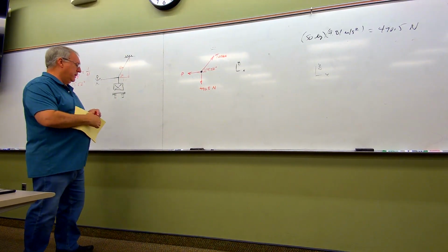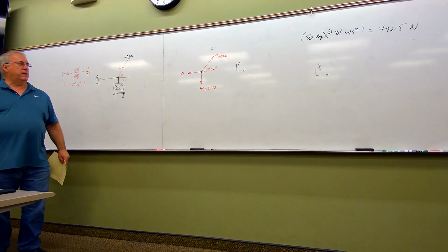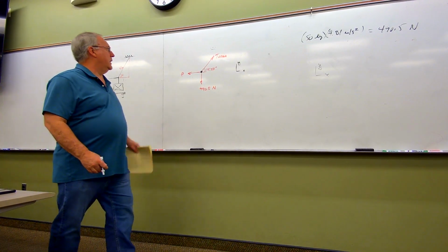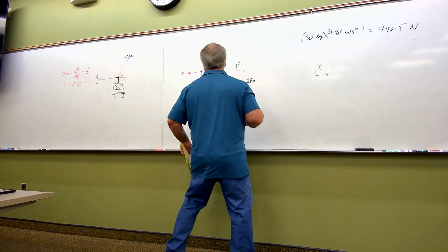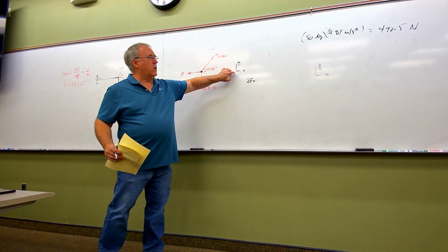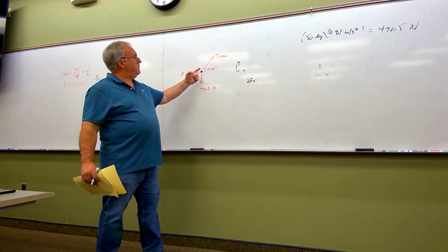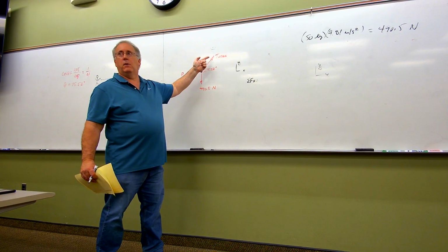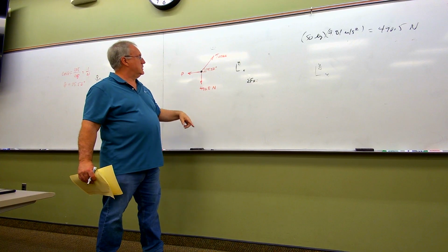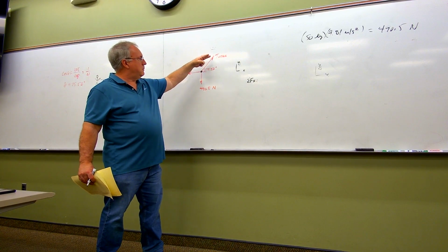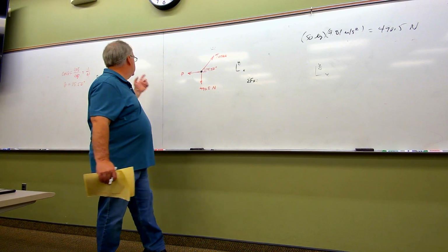Now we've got a free body diagram, folks, that at this point I would encourage us to solve. Let's remember we're looking for P right here. So let's sum forces in the X direction. Remembering that per our coordinate axis system, positive X is that away, I'm going to have the X component of T upper, which tends towards the positive X direction. The X component is T upper times the cosine of that angle, which we already know is 1/4.